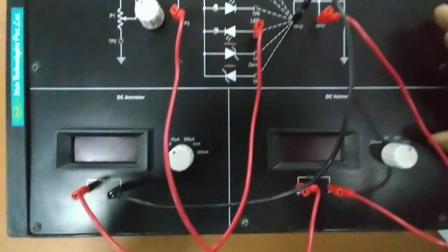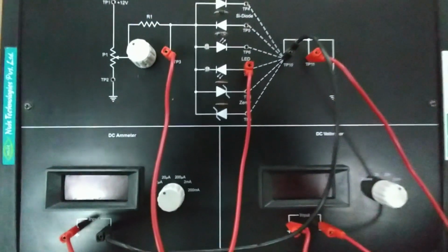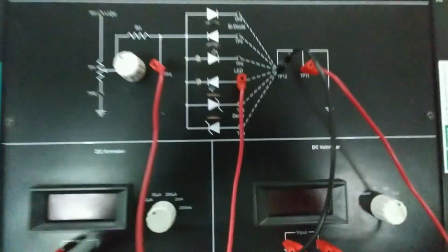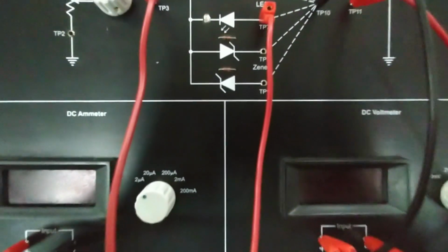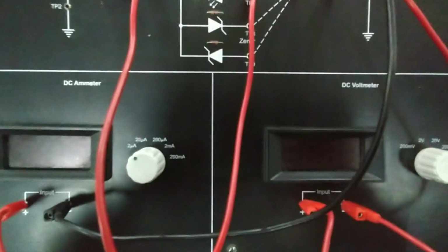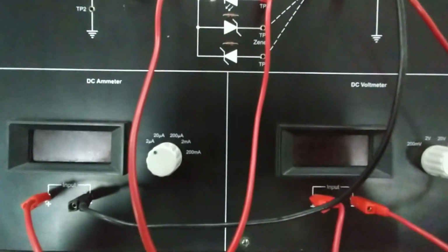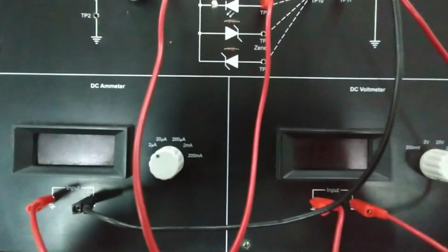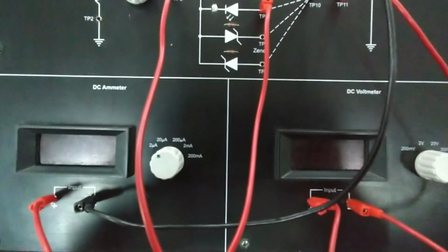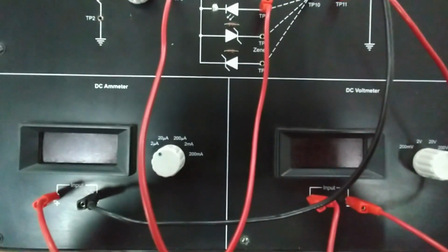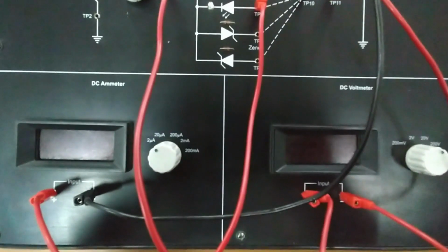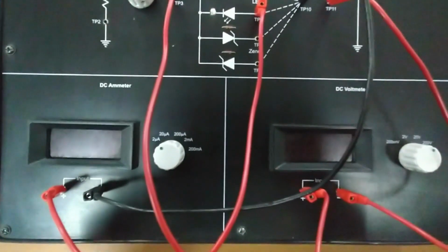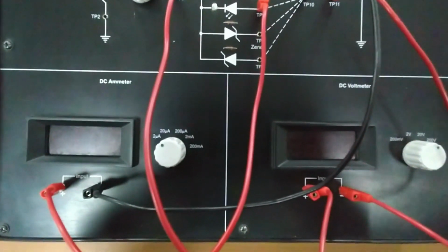and it is now measuring the current through the reverse bias LED. In reverse bias the current is very low and the supplied current is not sufficient to give any light out of the LED. So LED must be operated in forward bias. Hence LED is a luminescent device which emits light when it is under forward bias.